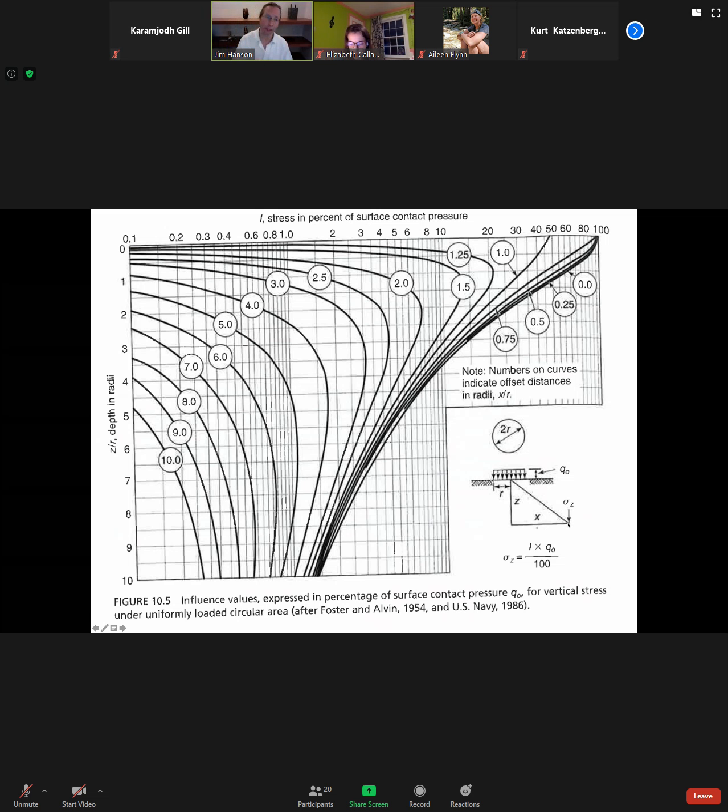area. This would be a classic application for, say, a petroleum storage tank, in which you have a cylindrical tank that's loaded a good portion of the year, and you need to sort out what settlement will be occurring, and do you have a forgiving enough membrane at the base of that tank to allow for appropriate service in that environment, sort of thing.